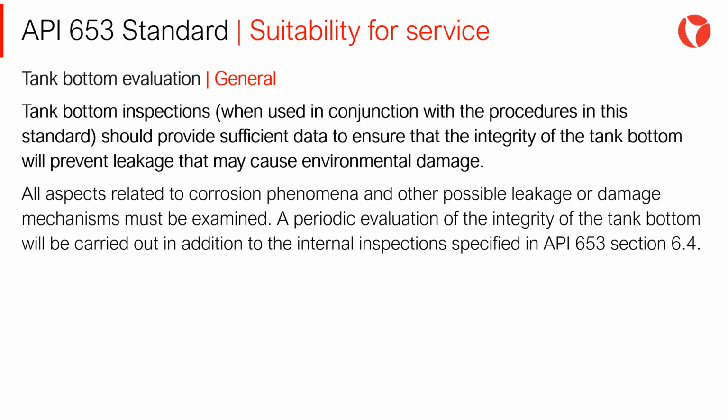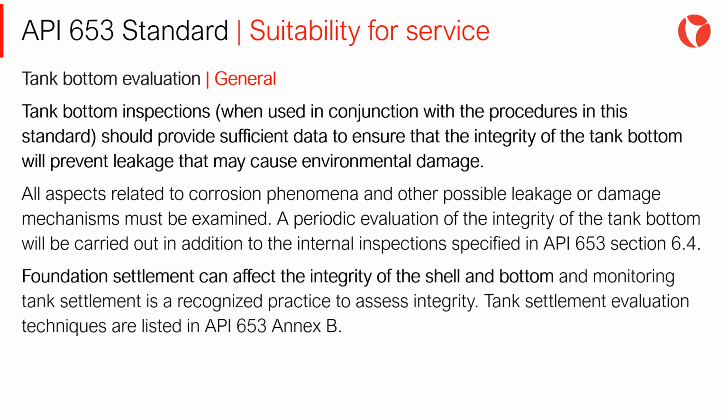A periodic evaluation of the integrity of the tank bottom will be carried out in addition to the internal inspections specified in API 653, section 6.4. Foundation settlement can affect the integrity of the shell and bottom, and monitoring tank settlement is a recognized practice to assess integrity. Tank settlement evaluation techniques are listed in API 653 Annex B.